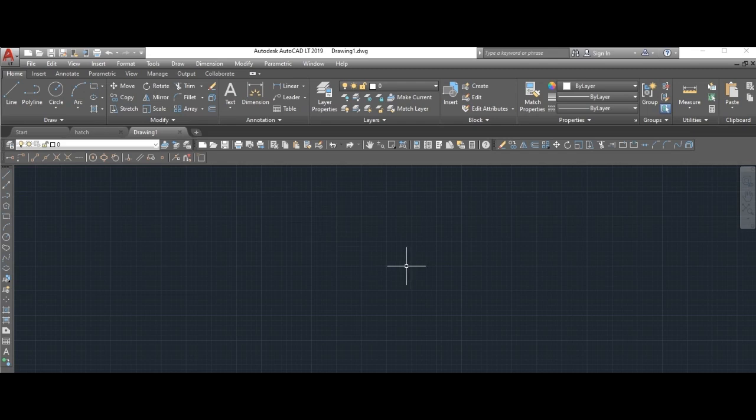So the first thing we are going to do, we pick the line tool, we come to a position, we click here. You can decide to draw direct or you give a dimension. So let me start. Remember our dimension has been set to millimeters, so I type 500 millimeters downward. I press enter. So this is 500 millimeters. So I come to this point, I put the mouse pointer in this direction. I type the distance to be 250. I press enter. Okay, I come down here, I type it to be another 500.